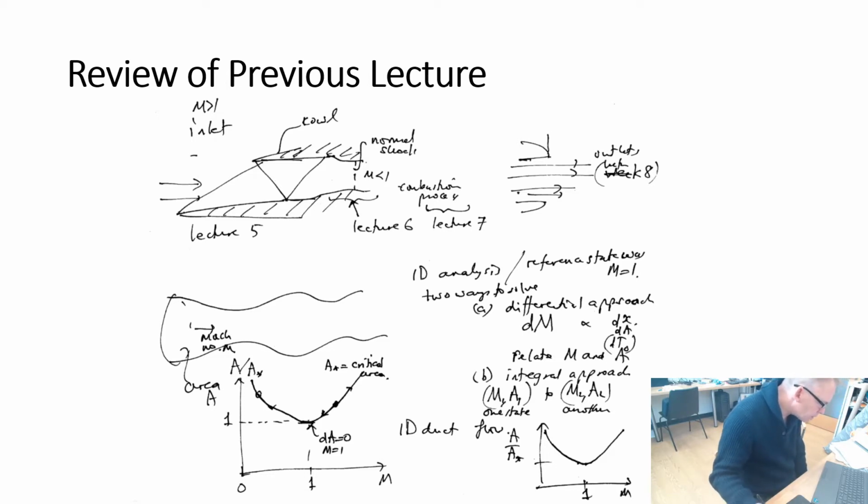Now, one of the things that was quite important when we were discussing flowing ducts, Lecture 6, was this idea of critical values. The reference state in this is the value when the Mach number is 1, and contrasts with the case when we were looking at normal and oblique shocks, where we're using the stagnation reference value for the temperature. Let's just remind ourselves that the stagnation temperature is a conserved quantity